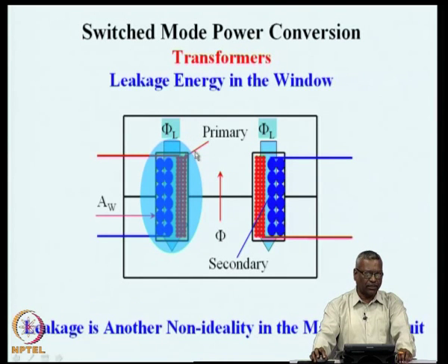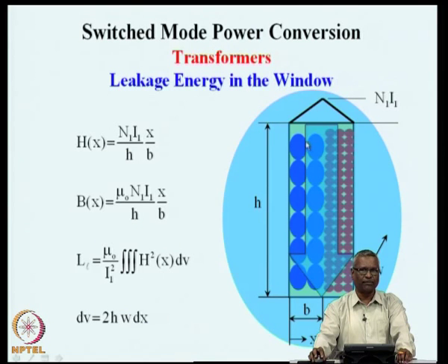The method to find out this phi L is to identify or understand the magnetic circuit here. The window is a completely non-magnetic material, copper conductors and air, and the top portion is a highly magnetic material, the bottom portion is a highly magnetic material, but the entire window is a non-magnetic material. So, it is possible to model this in a very simple way, with a highly magnetic material at the top and a highly magnetic material at the bottom.